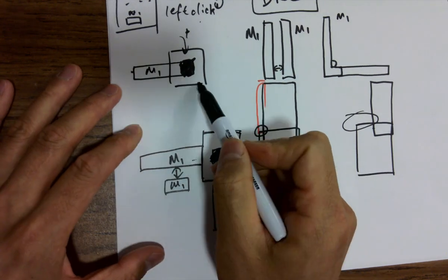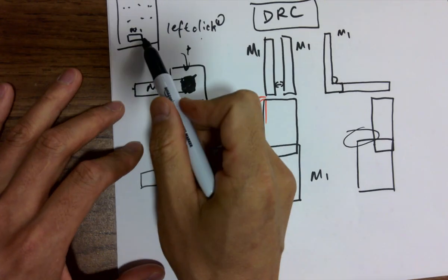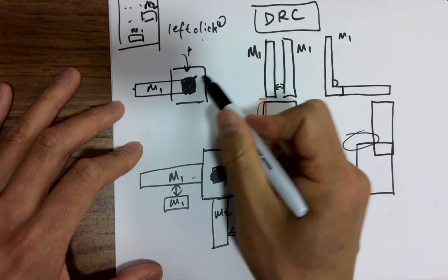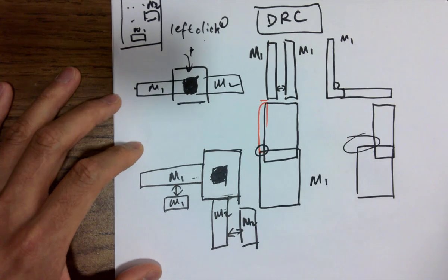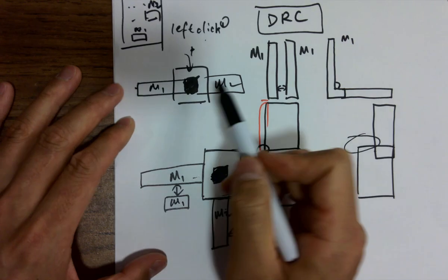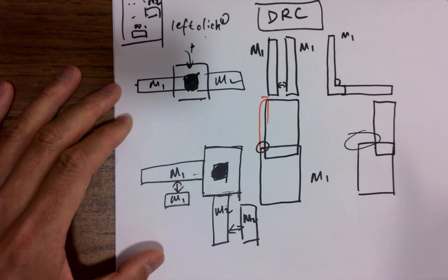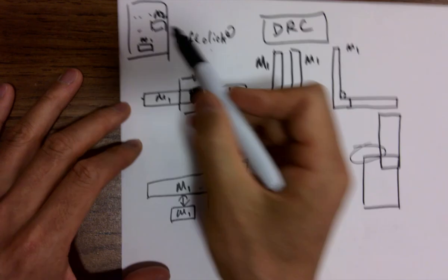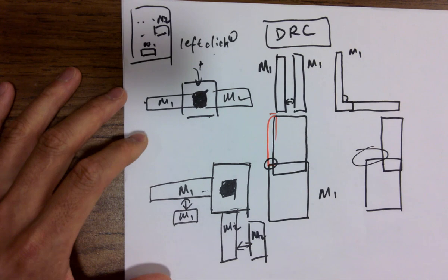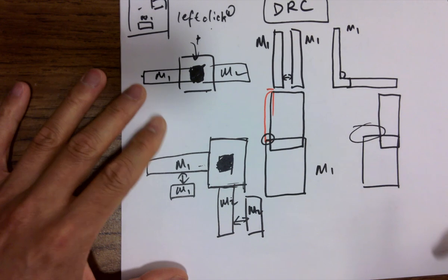So same piece of library component like this one, you left click, and then you go to the library, left click the metal tool component. So select the metal tool, and then you right click, it's going to introduce the metal tool. So depending on which one you select in the library. So this node can introduce both metals because it has both metals on the top of each other for this component, depending on which one you select in the library. It's just a left click and right click. So right click is placing a wire, left click is selecting something. Make sense? Okay.